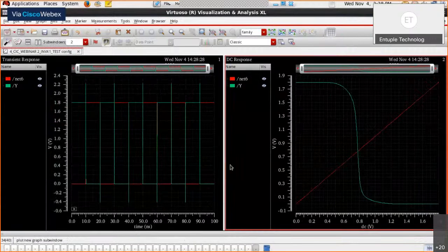You can measure the propagation delay. Compare the propagation delay for pre-layout as well as post-layout simulation, and check its impact. This is one of the methods of how you can check the impact of your parasitic components. Then you have some other methodologies also. This is the most basic one and most widely used option also.